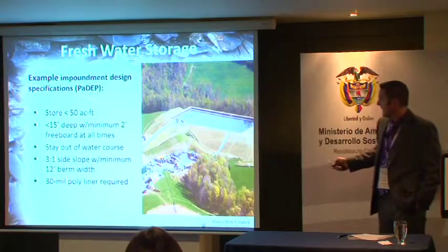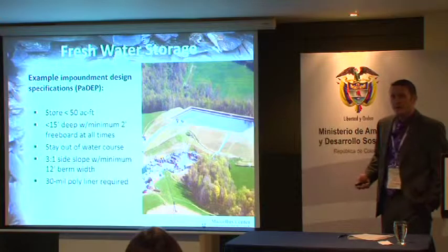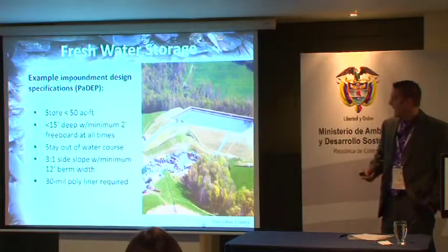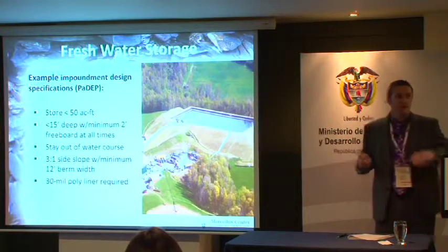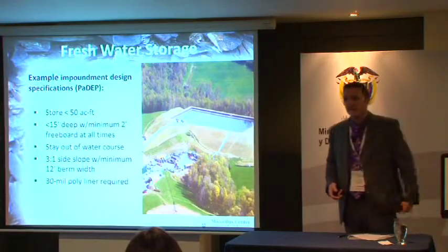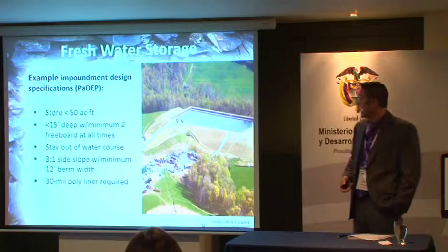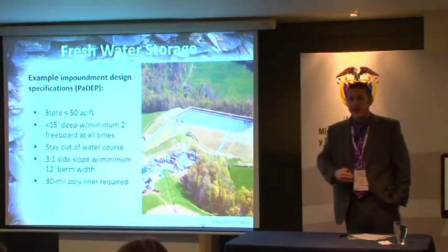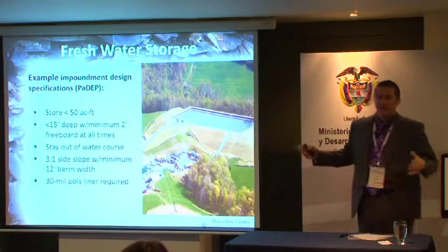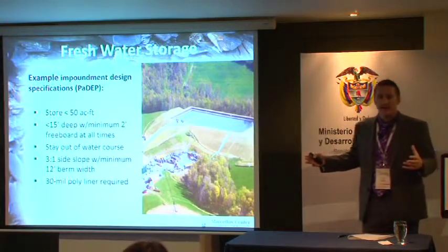So in Pennsylvania, they have to have a 3-to-1 side slope, and basically be less than 15 feet, or roughly less than 5 meters deep.